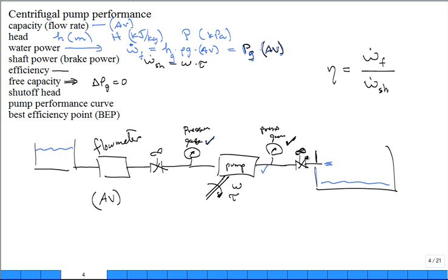And you know what? The motor's still driving that pump. The pump's still running at 1800 RPM or 3600 RPM, right? Okay. So what do you think the pressure in this outlet gauge does? It goes way up. And it goes to the maximum that it's going to go. And the suction pressure is still low. And now I have the maximum delta P across that pump.